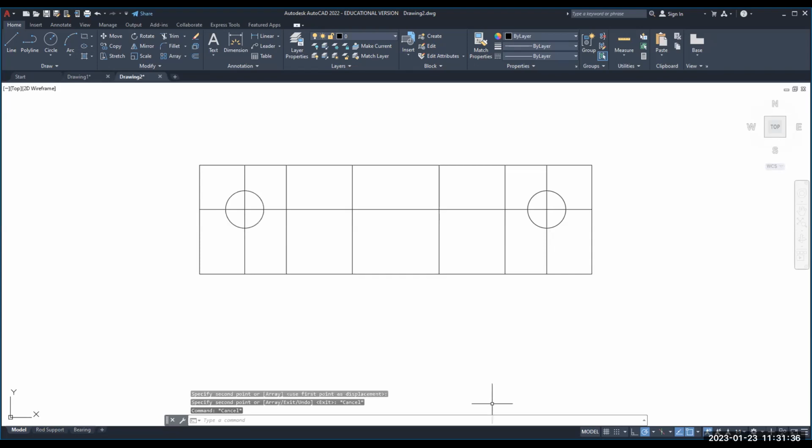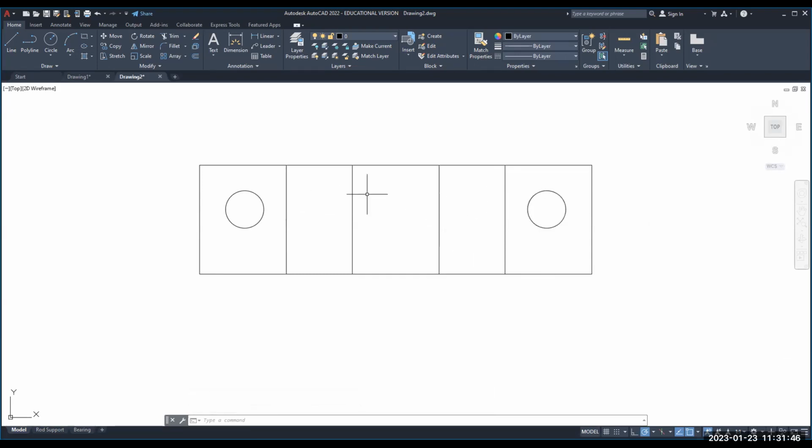All right. When you do that, you use construction lines, just make sure you get them out of there because they really confuse things. All right, that's good enough. There is some hidden geometry in here, and I have corners to chop off. I get that, but I want to do the section part because it's a little tricky to make the cutting plane line. You want to make a line that has arrows on it. That's a little trick, okay? And AutoCAD has no easy, fancy way to do it.